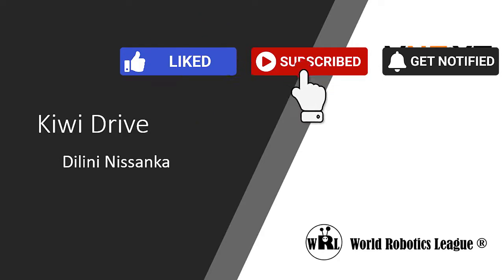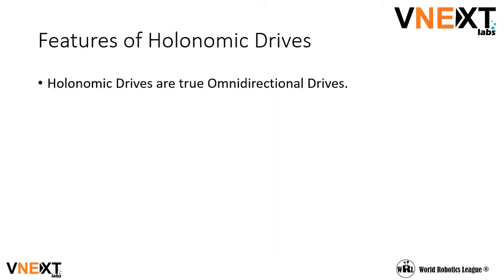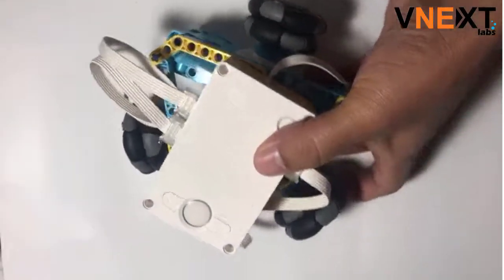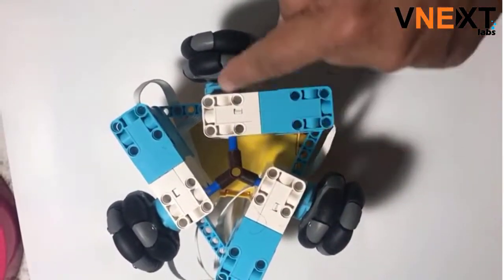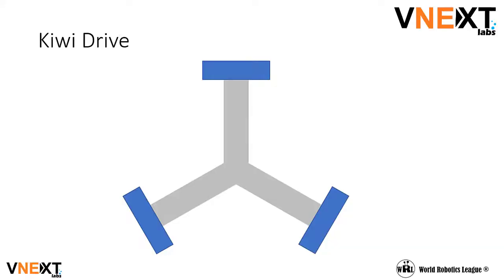In this video, I'll be talking about the Kiwi Drive train, which is a type of holonomic drive train. Holonomic drives are true omnidirectional drives, which means that they can move in any direction. A Kiwi Drive is a three-wheeled omnidirectional drive, and the wheels are 120 degrees away from each other. Here's a simple diagram of what the Kiwi Drive looks like.